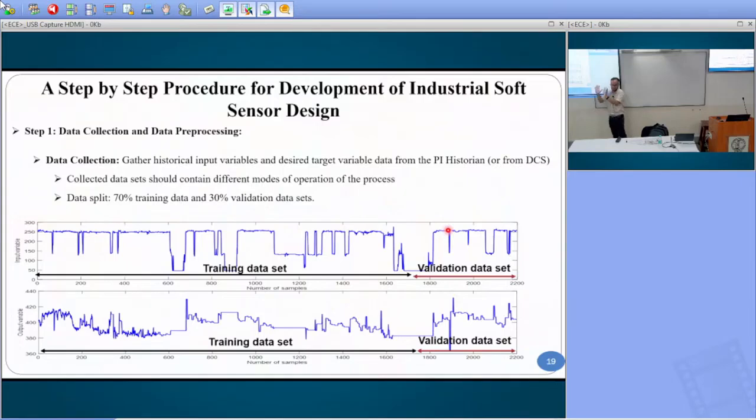So it's needed, but there are other points where you can see some spikes. These are for a very short time, within 1 or 2 samples the spike is there, and then it gets back to the normal point. So these are the outliers, like sensor failed data. Here you can see again there are some data points which suddenly drop within one sample.